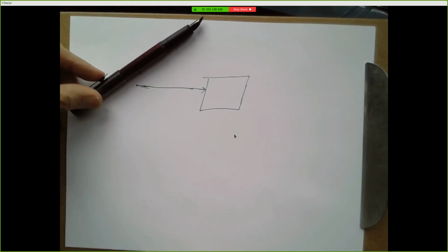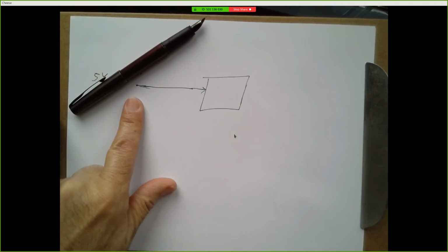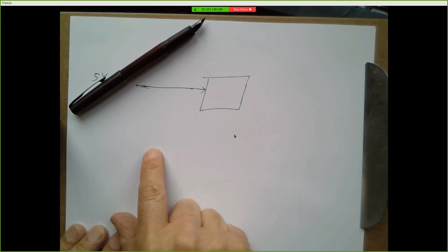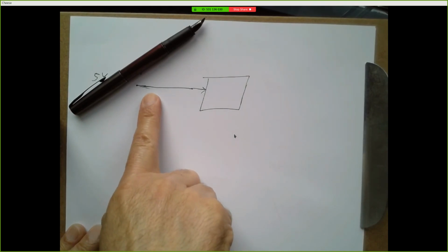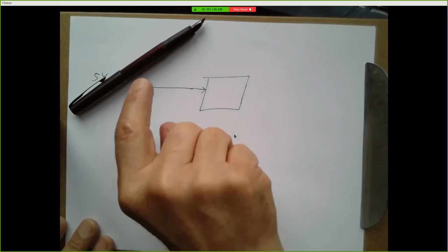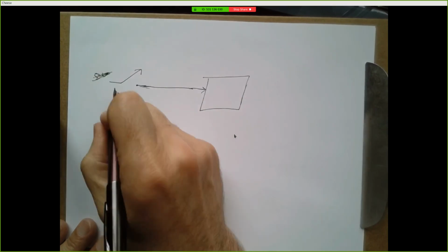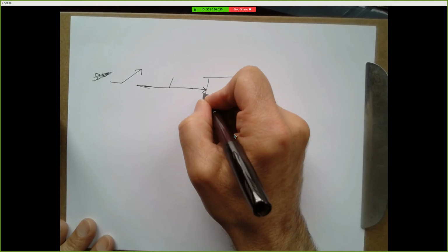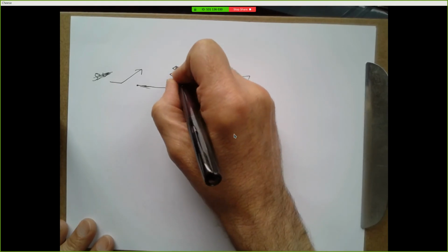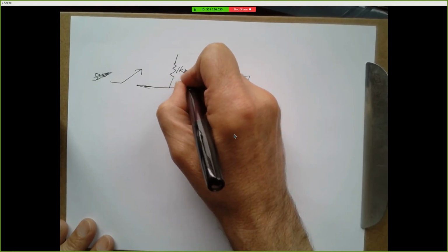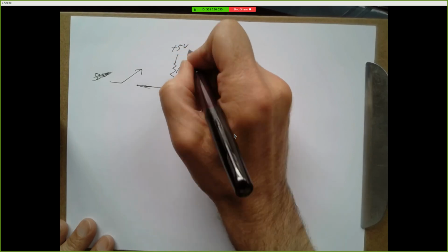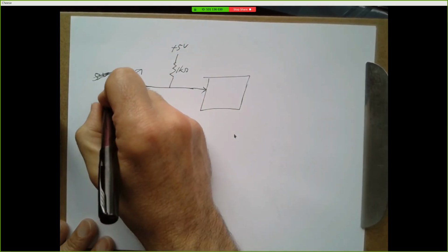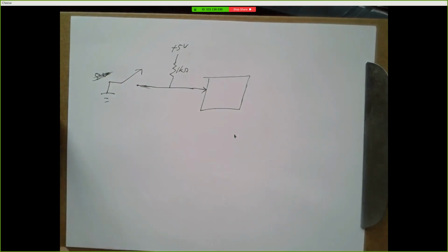Okay, this is really important. A disconnected input is not the same as an input connected to 0 volts. A disconnected input is basically undefined. So here's how we can use this simple switch to feed in a 1 or a 0. Take the signal that you want to generate, connect it up through a 1 kilo ohm resistor to 5 volts, and then also connect that input signal to a switch, which can be used to connect to ground.